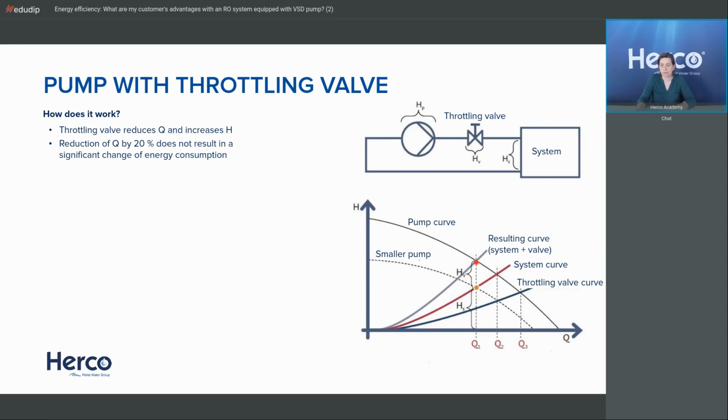So I need to move back to my operation point. If I have a throttle valve, there's only one way to do that. So I will close the valve slowly, and this is the pressure loss the valve produces, the dark blue line, when it is closed, okay? Or half closed or whatever.